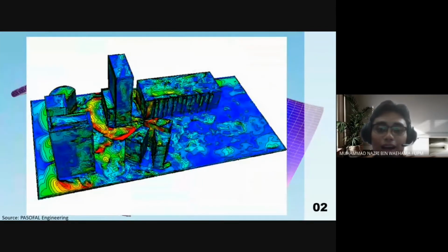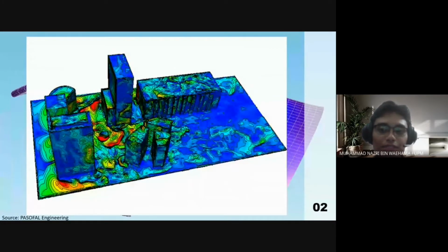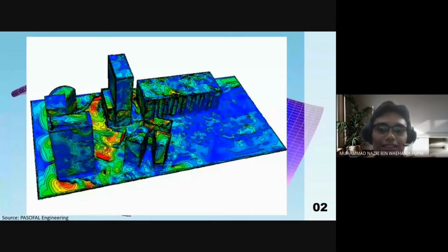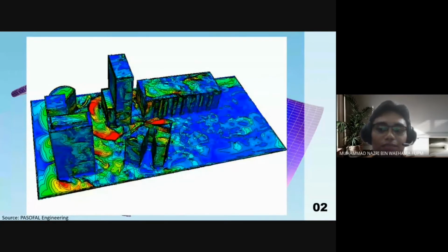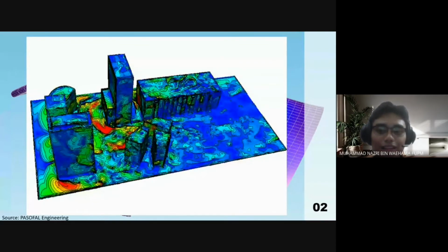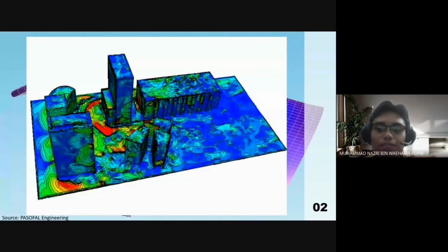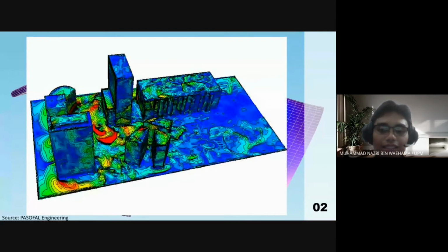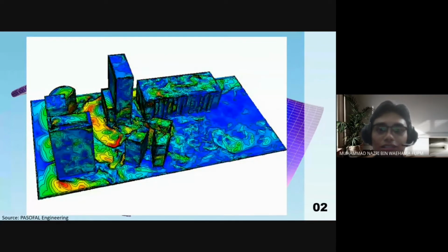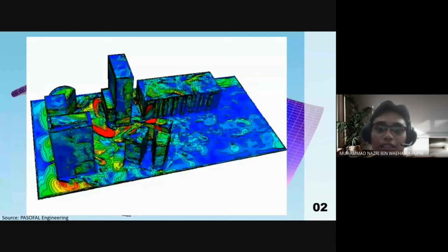Next, simply expressed, this approach is extremely beneficial for tackling problems involving complex geometries, loading, and material characteristics for which analytical solutions are unavailable. The finite element approach includes simulating a structure with tiny linked elements known as finite elements, as you can see from the figure above. Each finite element will be assigned a displacement function, and every interconnected element, including nodes and boundary lines, is linked to every other element, either directly or indirectly through common interfaces.